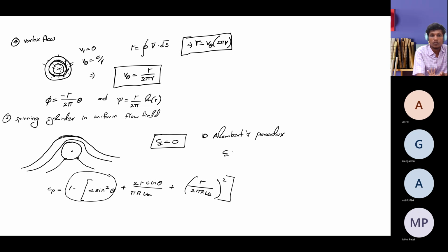That is, drag is finite from the experimental result, where we have the viscous effects and other effects, pressure drag also. There, your drag is finite, but theoretically it shows the drag is zero because we did not consider any viscous effects while deriving the pressure distribution and forces on the spinning cylinder. So this is mostly famous in aerodynamics, the D'Alembert's paradox.